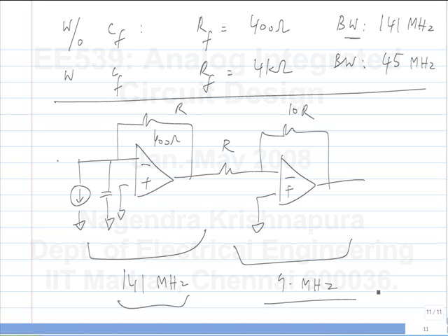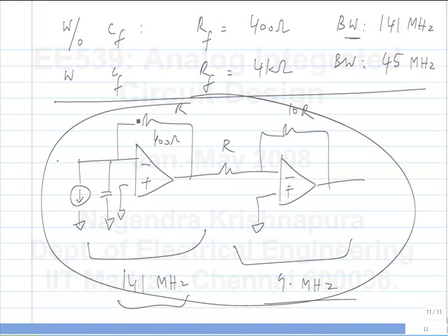And we haven't discussed it yet, but the input referred noise of this is a more noisy circuit than the other one. Okay. So in general, to get the best noise performance, you should amplify the signal to a high level in one shot. That will make sure that the signal is above noise. So this is kind of philosophically, you will see later through simulation also that this is true.